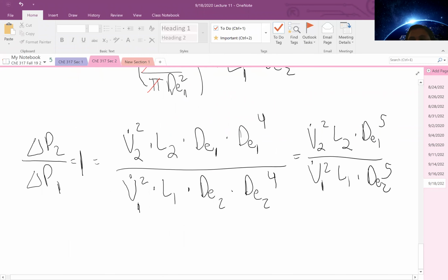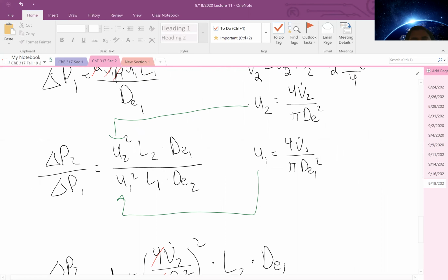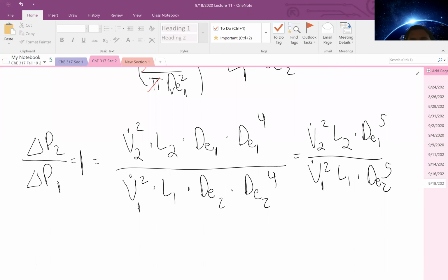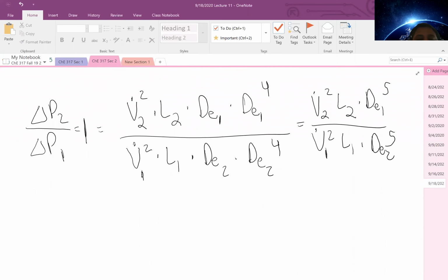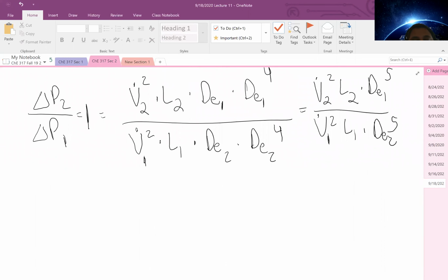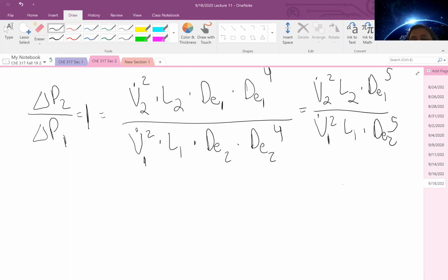And so what you can see here is without actually having to do my mechanical energy balance and solve for those pressure fluctuations, I can simply do this exercise to look at, based off the key terms, what are going to be the primary factors in changing this pressure for the system that I've identified. We'll use this a lot in design too. However, I think it's really worthwhile to illustrate this technique here, because I know what L1 and L2 are. I know what my effective diameter 1 and my effective diameter 2 is. And so that means